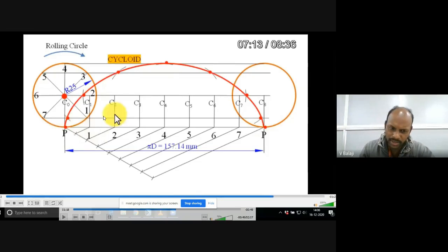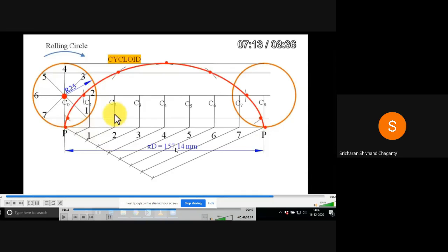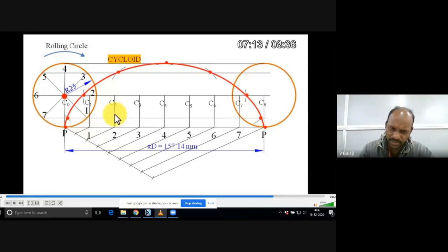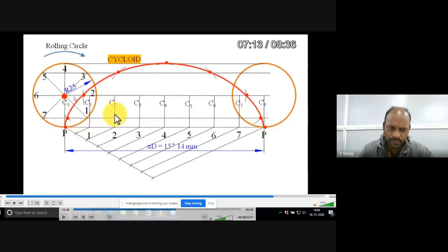Sir. And coming to the letters and numbers, okay. Letters like C1, C2, these letters, radius R, capital R. So these numbers and letters, you can use HB pencil, dark pencil. Okay. Remaining all other lines must be 2H pencil only.